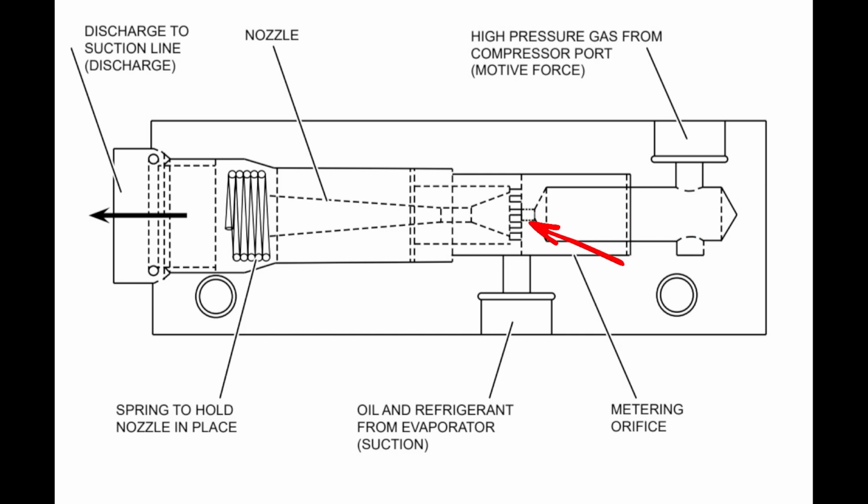And that's also where this nozzle is our pressure separation as well, so that this isn't just a hot gas bypass. So when we're flowing through here, because we've got this nozzle and there is a pressure separation happening, that is preventing this from just hot gas bypassing directly into our suction or our oil tank, which is going to create a whole other slew of issues. So just bear that in mind. But just from an overall, basic level, this is what the internals are trying to accomplish of this eductor system.